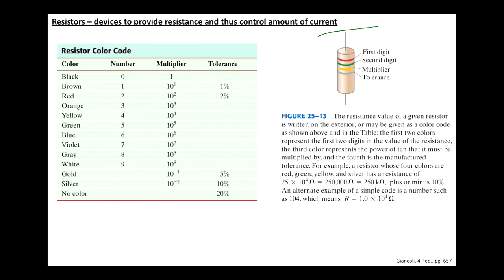Resistors are just devices that look sort of like this, and they have a neat little color code to help us understand how much resistance is there instead of just printing the number on there, because often it's quite small. It's easy for me to see colored bands, but it would be difficult perhaps to read numbers that are on there. So you can see that there is a resistor color code made up of 4 different bands, and it simply works this way. Notice the one that we have here starts with a red.